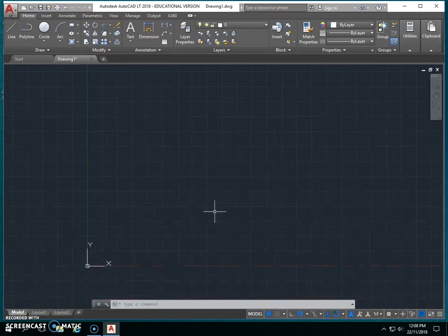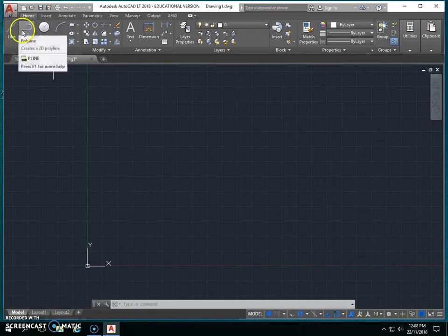I can zoom in and out with my mouse. Typically, you're not really encouraged to do that, but that's fine. There's another thing you should not encourage, which is to use Control-C or Control-V for copy and paste, because there's a function in AutoCAD that has copy, and it's very useful. That said, it's no longer as bad as it used to be if you do that. The main commands that you really want to use are line, polyline, circle, and arc. They are the main commands that everyone wants to use.